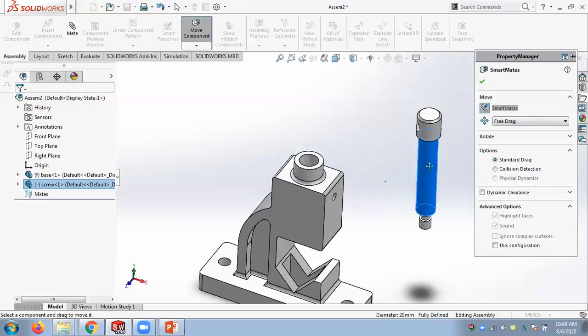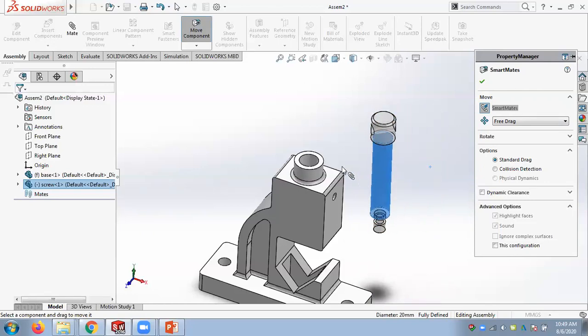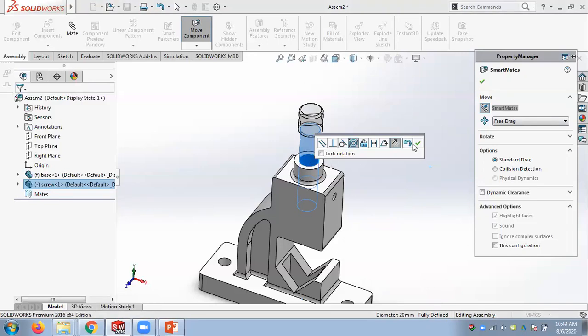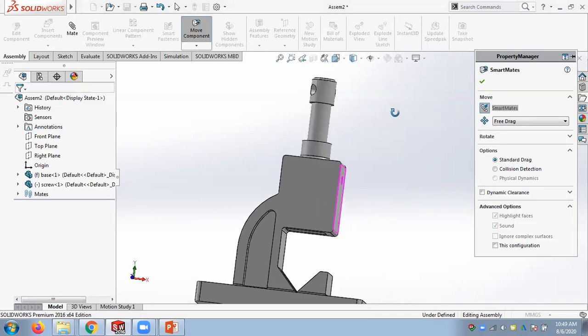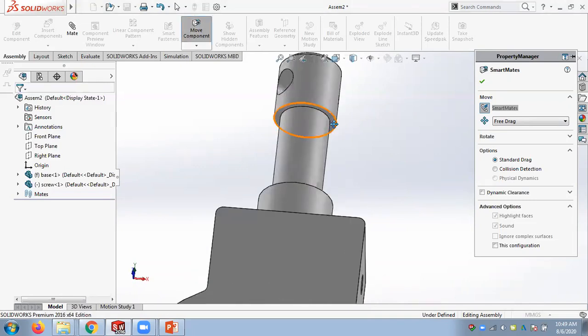You have to double click on this. So when you double click on the face here, this is turned into a clip mode, and this is going to be transparent. So you can just drag and drop to this hole. So you can see it's now working. Concentric symbols appear. That thing automatically happens. Press OK.